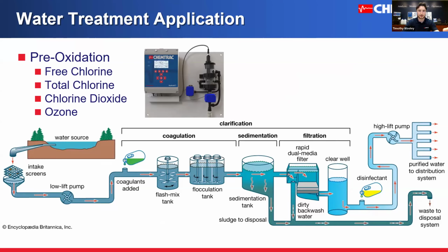By removing these contaminants before you get to the main treatment process, this enhances the overall efficiency of water treatment systems. Chlorine is incredibly effective, as we all know, in removing things like germs, but also soluble iron and manganese, as well as organic micropollutants. However, it can produce harmful disinfection byproducts, or DBPs, as we call them, when it's reacting with natural organic matter.